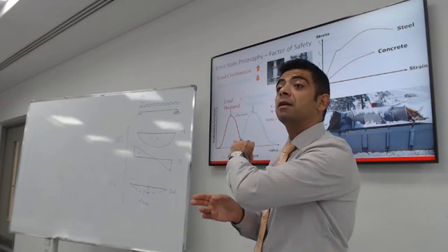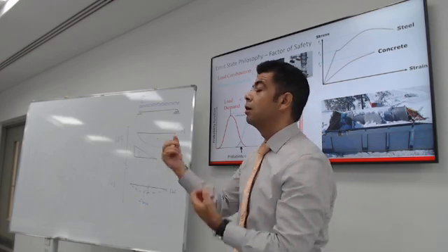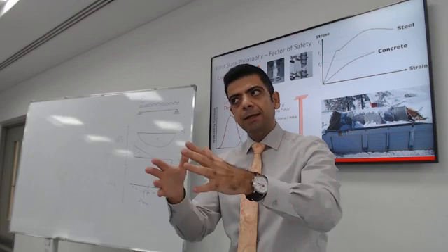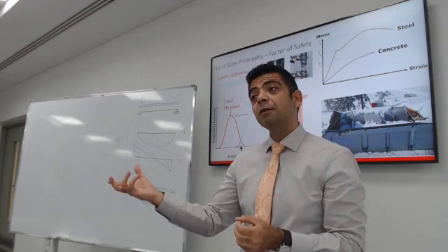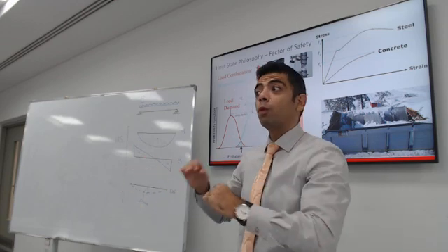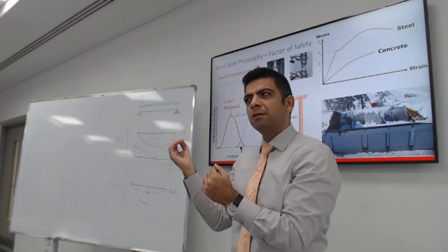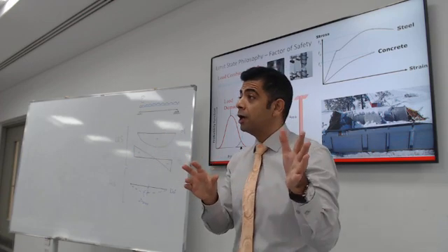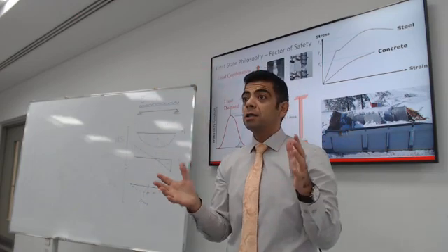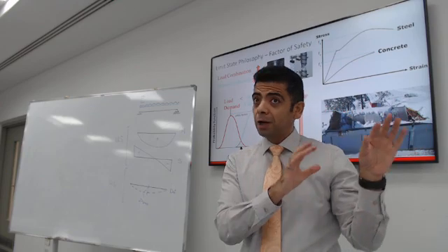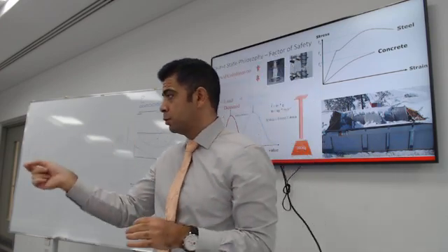They come up with it from the probability that there is a percentage that the wind load or the snow load might exceed the design value. Same thing with the material. Steel usually is produced in factories with very precise measurements, so the factor of safety or the reduction in material is usually small. Concrete is mixed on site. You can have it mixed in trucks, so there could be more variations, so you need to take a different reduction factor for different materials. We'll revisit this every time we choose to design a new material.